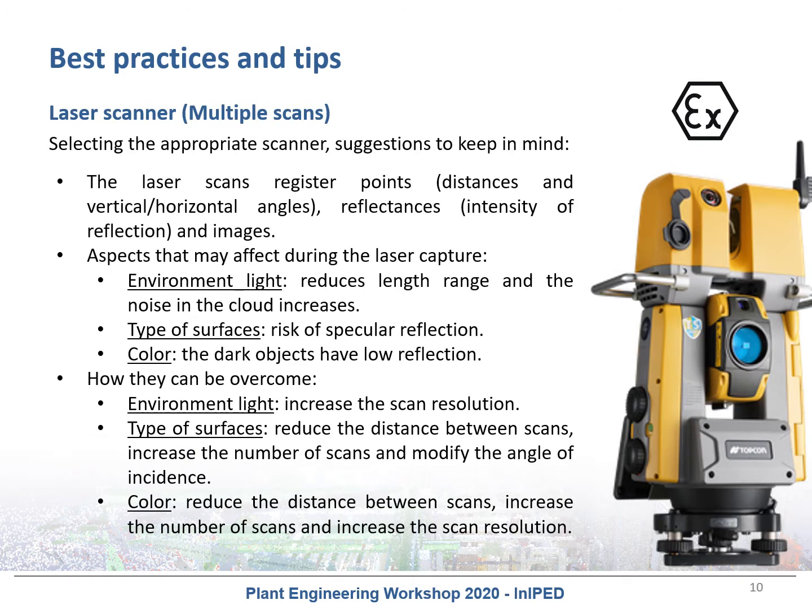You have to keep in mind that in the point clouds you will see some areas with shadows or discontinuous pipeline routings. These problems can be caused by environmental light, the types of surface, shadows between objects, or the location of the scanner. As I said a few minutes ago, usually the scans are taken by an external company.